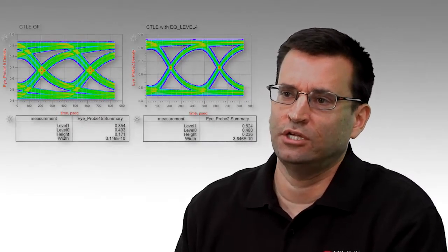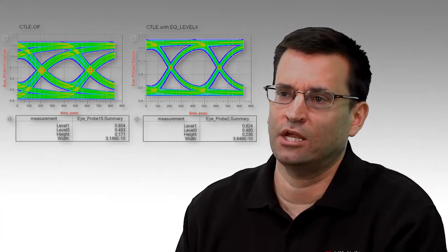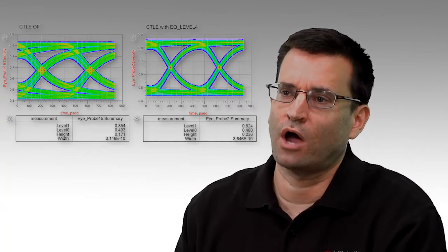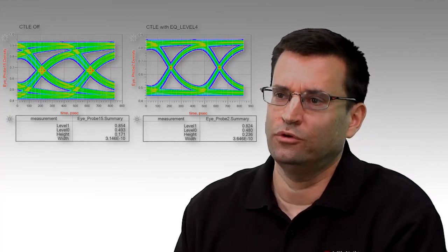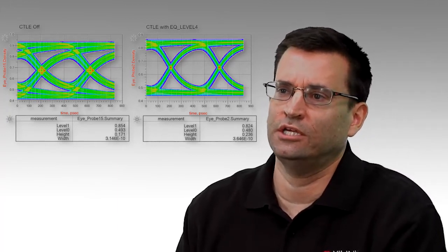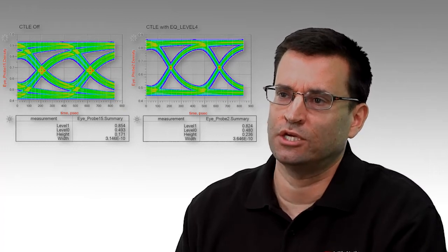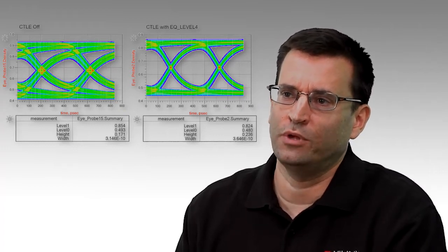You can see from the simulation results that selecting the appropriate CTLE gain settings generates a larger eye opening than when the CTLE is disabled. You can cycle through the various CTLE gain settings in your simulation to optimize the eye opening for your specific channel characteristics.